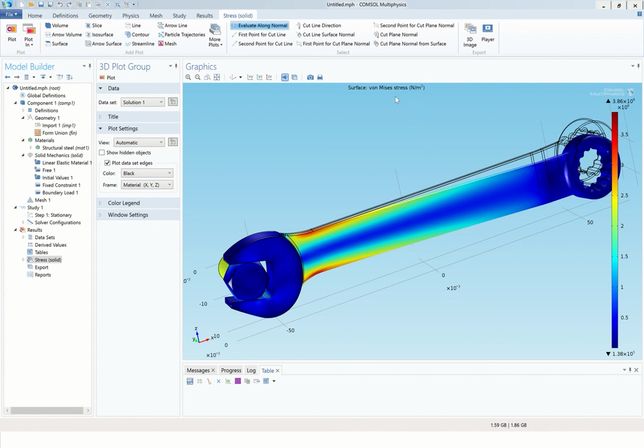And so again, the von Mises stresses are taking into account all the different stresses in the multi-dimensional, multi-axial directions and finding where the greatest stresses are occurring. So this is again where we ended up in the last class, where blue is the lower stresses and red are the higher von Mises stresses.